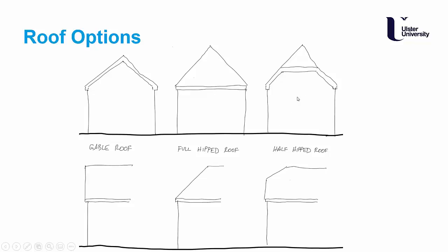So this is the side elevation. One of the things that does need to be considered here is where the rainwater will go once it reaches the bottom of that roof. So what do you do if you put a gutter on there, and where does the downpipe go, or the rainwater pipe? Do you dress it round onto the roof, or is there some way of taking it down to ground level on that side elevation? The front and the rear would be mirror images of one another, looking like this. And again, this angle would be maybe 45 degrees. It just helps to soften the look maybe of the dwelling.